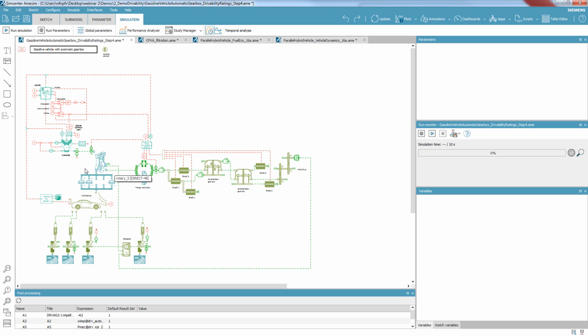Thanks to Simcenter scalability, we can easily select models that will predict the torsional deformation in the driveline, taking into account the shaft and the friction components' stiffness, but also the stiffness and the damping generated by the tires and the suspensions, considering a 3 degrees of freedom vehicle model. Such a model can take into account the longitudinal motion, but also the vertical one and the pitch. In this model, we will also consider the reaction of the powertrain on the car body through the engine mounts, using a 3D model for the engine block.